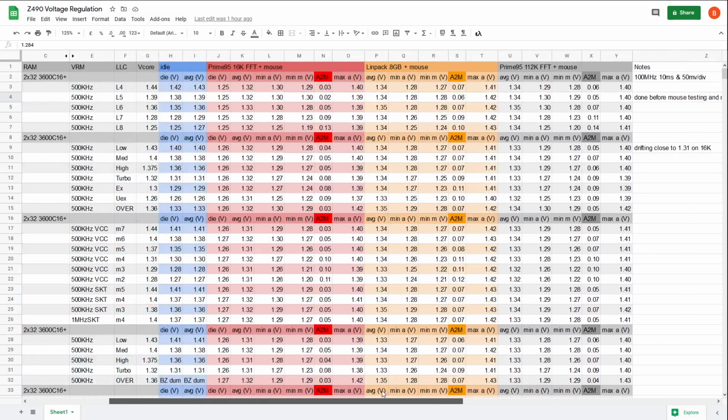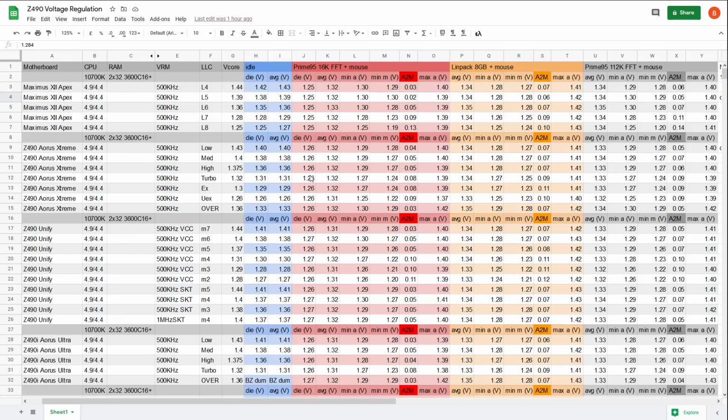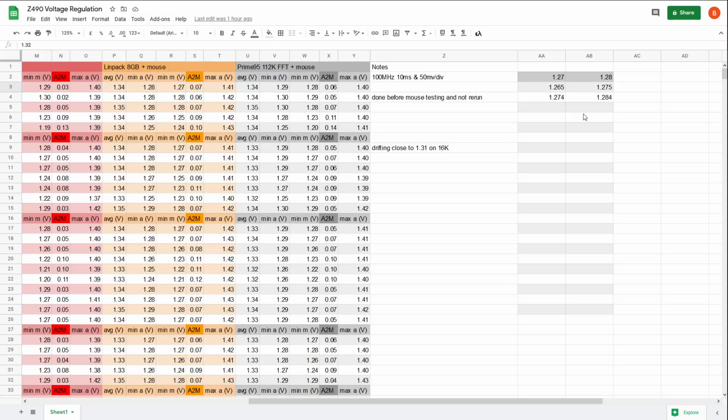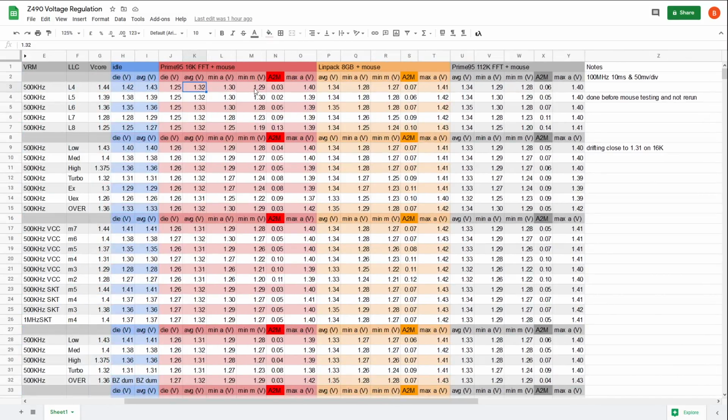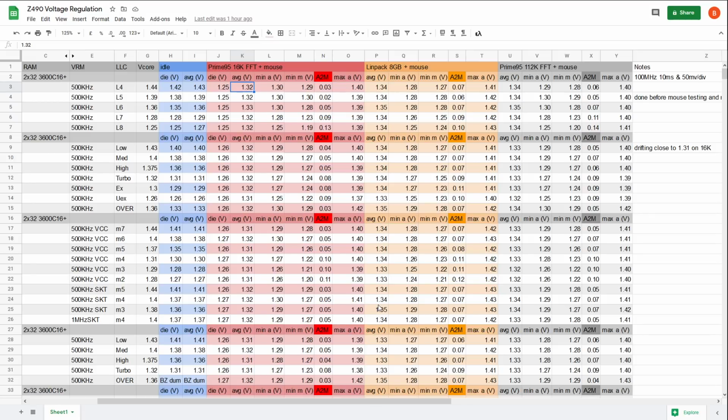Technically, there's a bit of a workaround that I could have done, which is to run the same tests multiple times with slightly different voltages. So instead of doing everything with the goal of hitting 1.32 volts on the average oscilloscope-measured voltage, I could have done tests at 1.32, 1.34, and 1.36. That would give us more data, and for comparison purposes it would be better. It still wouldn't change the fact that the measurements are to 10 millivolts, but if there's one measurement that looks a bit weird, having multiple reruns of that same measurement at different voltage levels would smooth over that irregularity in the data.